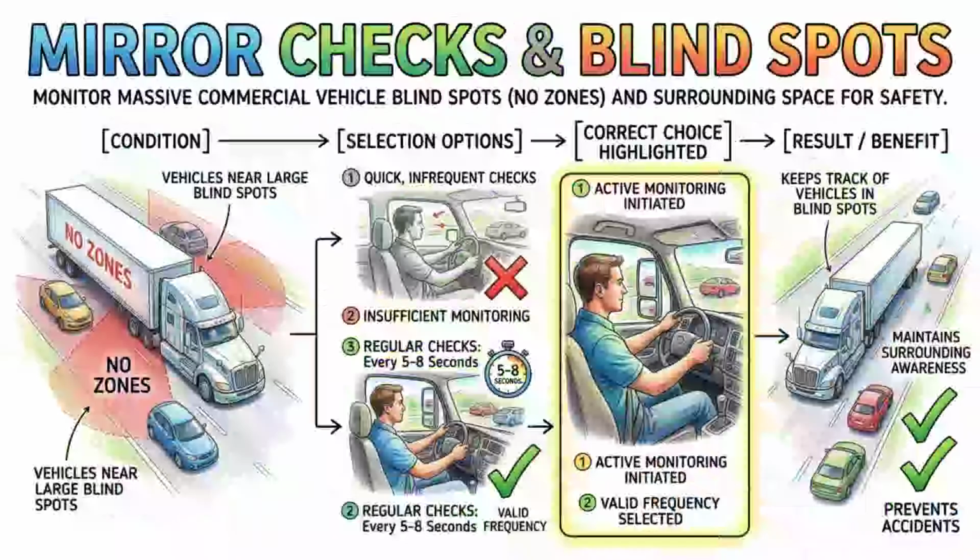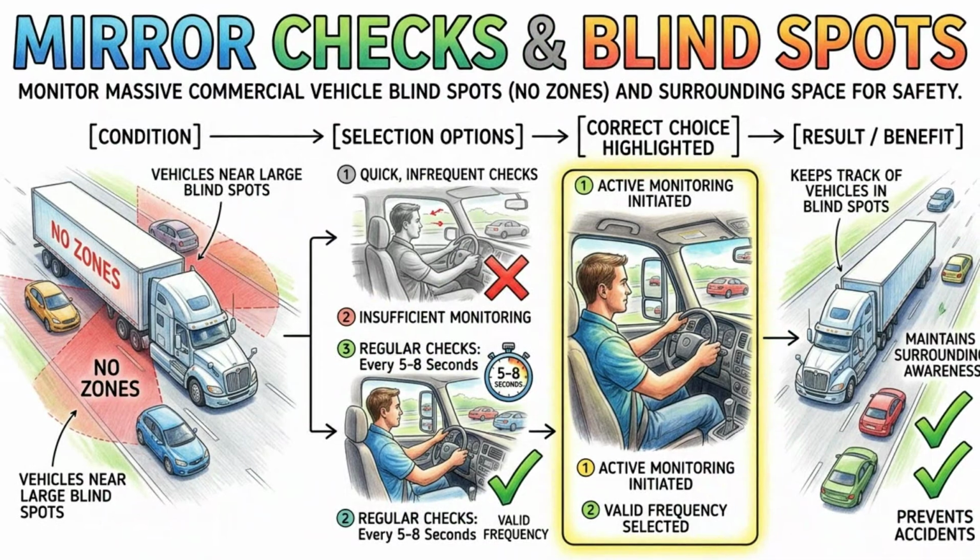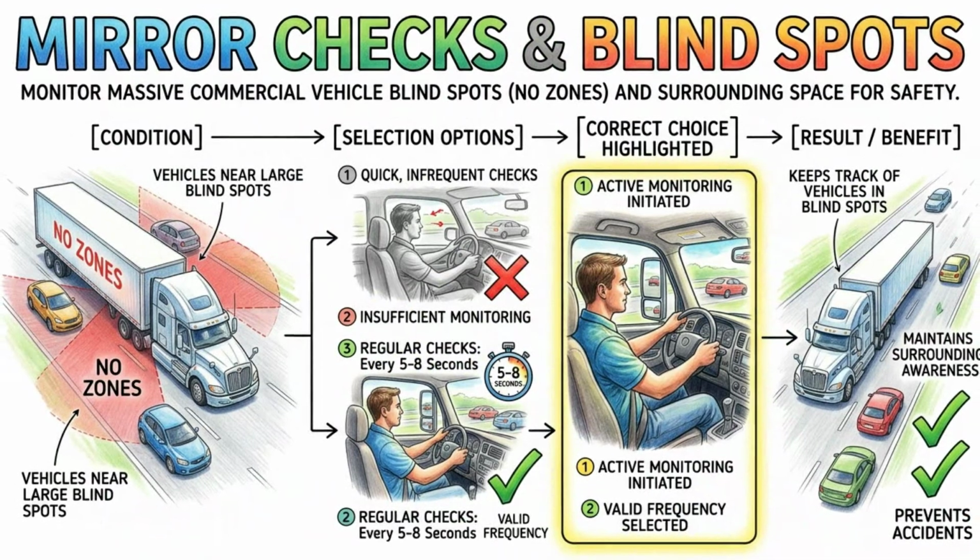While we will cover air brakes deeply in a later section, you must know basic brake components for the general knowledge test. At each wheel you will check the brake hoses and lines to ensure they are not cracked, worn, or leaking air. You must also inspect the brake chamber to verify it is securely mounted and not dented. Finally, you will look at the slack adjusters and pushrods, ensuring that with the brakes released and pulled by hand, the pushrod does not move more than 1 inch. This 1-inch rule for manual slack adjusters is highly likely to appear on your multiple-choice exam.